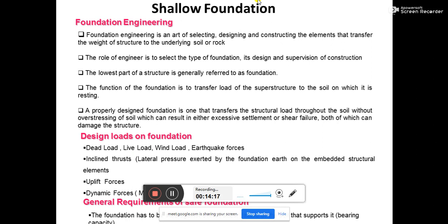about consolidation, if you see. So, the consolidation, whatever you have learned in your 4th semester course of soil mechanics, that consolidation deals with the settlement of the structure, right? And that settlement calculation is also very, very important. So, your foundation should be designed such that it should not be excessively settling. If it goes beyond the settlement limit, then your foundation will fail. So, you should be very cautious about these two criteria while designing any foundation, or while selecting any foundation, while designing any foundation, while constructing any foundation.